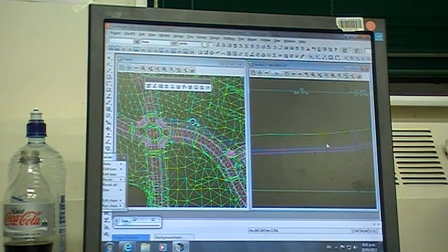Do you know what he means by trenchless technology? Yeah. Directional. Which will tend to end up, obviously we don't use concrete pipes. Then we'll end up with a PE or something like that. A PE with an NCN 16 rating, so that it's got a certain strength.